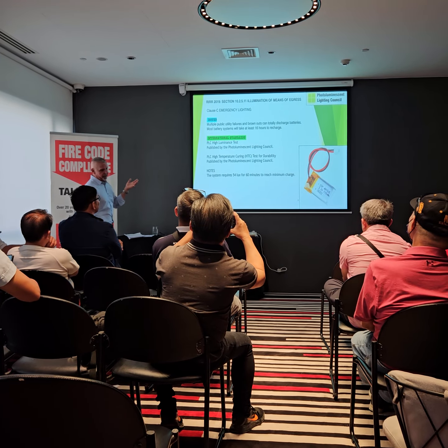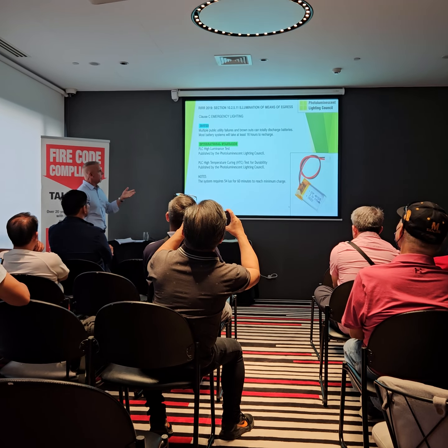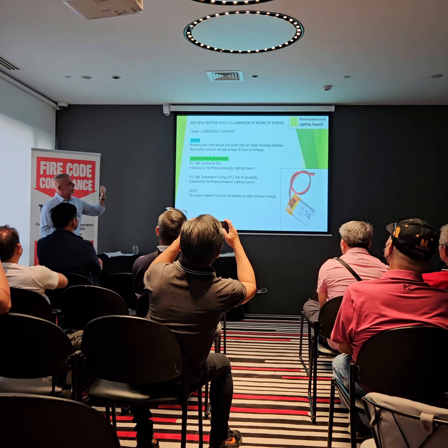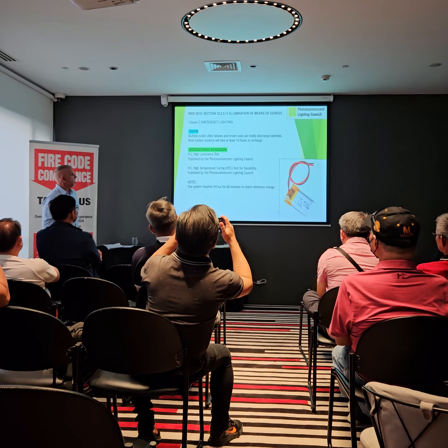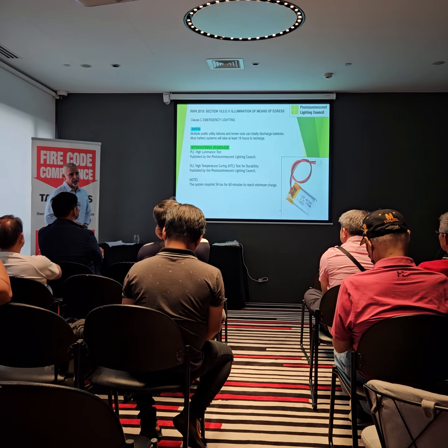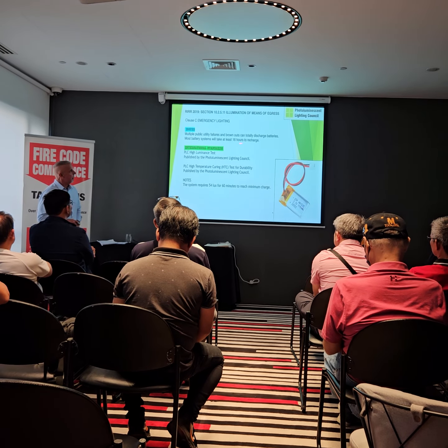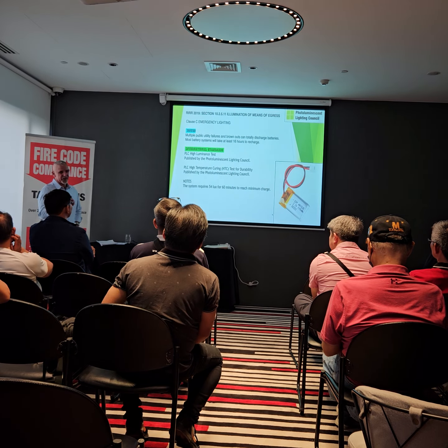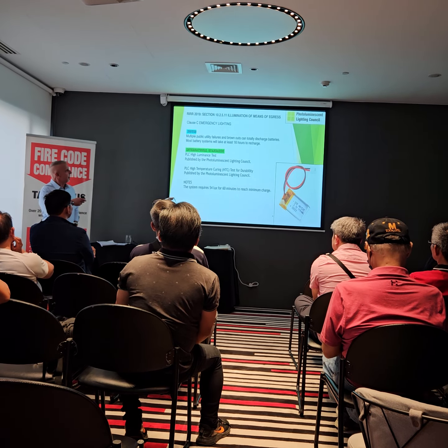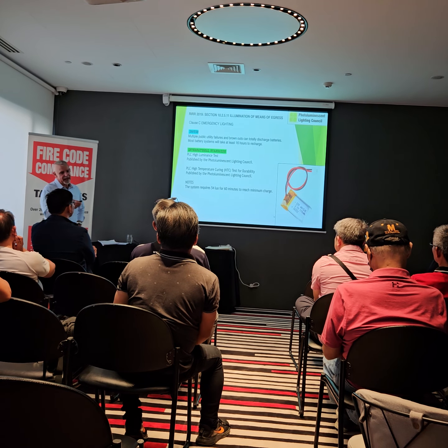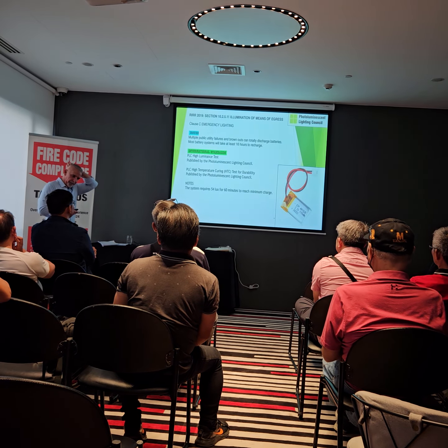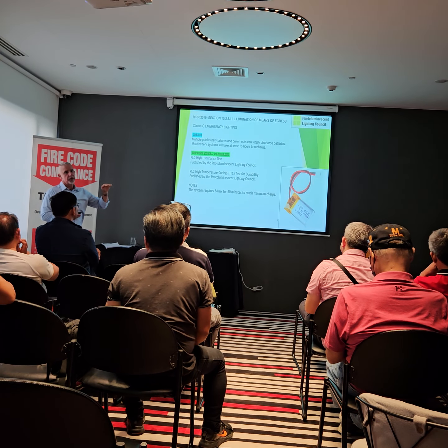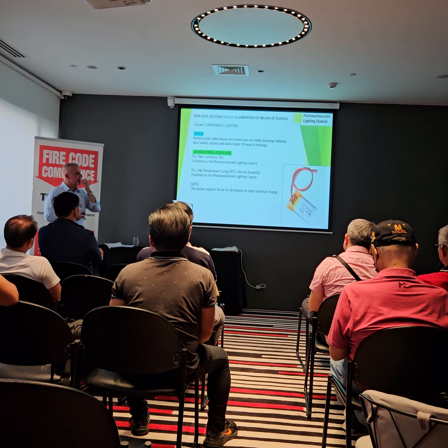The other thing that photoluminescence does is recharge really quick, and I mentioned this earlier. Whether it's an exit sign or emergency lighting system, they do take a long time to recharge once they're fully discharged. 16 hours is the mark that we use, because that's the maximum recharge time allowed in most emergency lighting standards around the world.